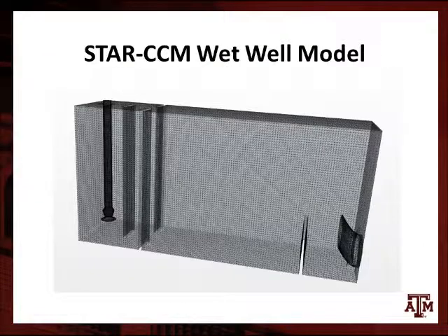So here's a STAR-CCM+ wet well model, showing a physical model of our wet well using STAR-CCM+ to validate the dimensions that we chose for our wet well, and whether they would be sufficient to allow the sand to settle out before it is pumped up into our pump, causing failure in the system. And in here you can see the intake pipe where the water is introduced into the wet well, and the sand baffle before the pipe, and then the baffles used to represent the vertical band screen, and the vertical turbine pump is shown as well.